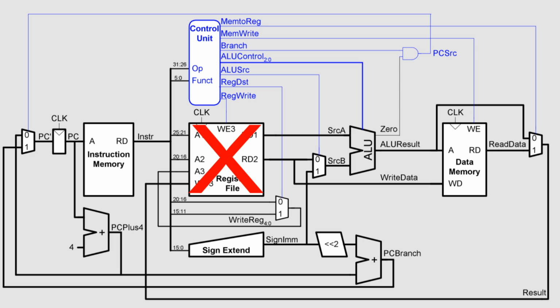This means that we can temporarily turn off, or cut current to, circuit blocks that are not in use. In addition, a similar method can be used to power down arithmetic units that aren't being used in a particular clock cycle. An example is a branch that probably won't use the multiply function.